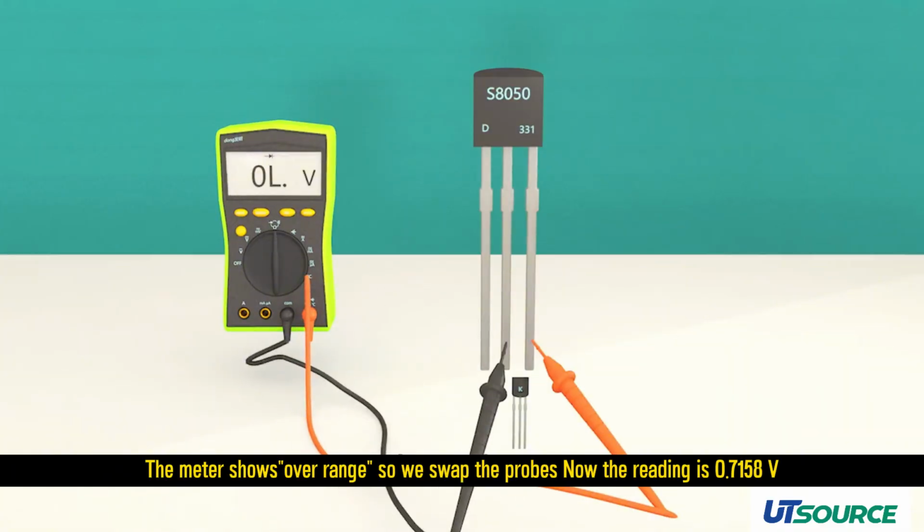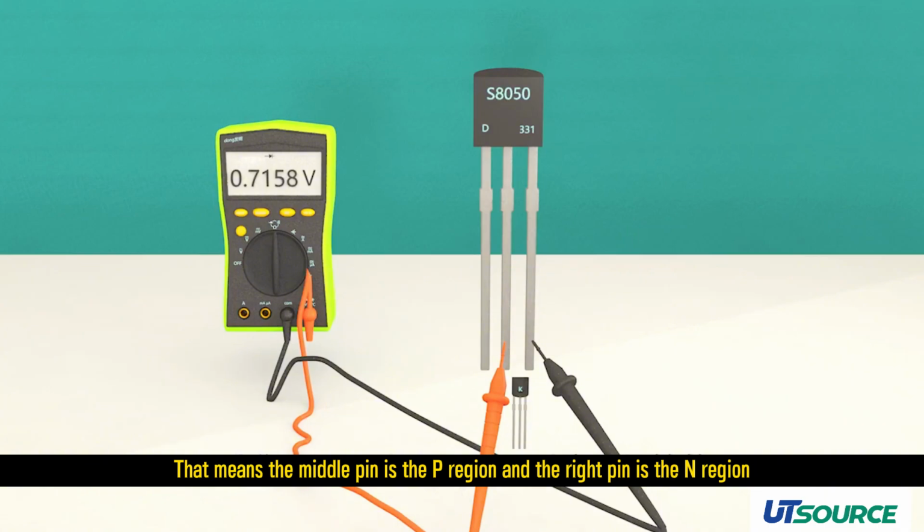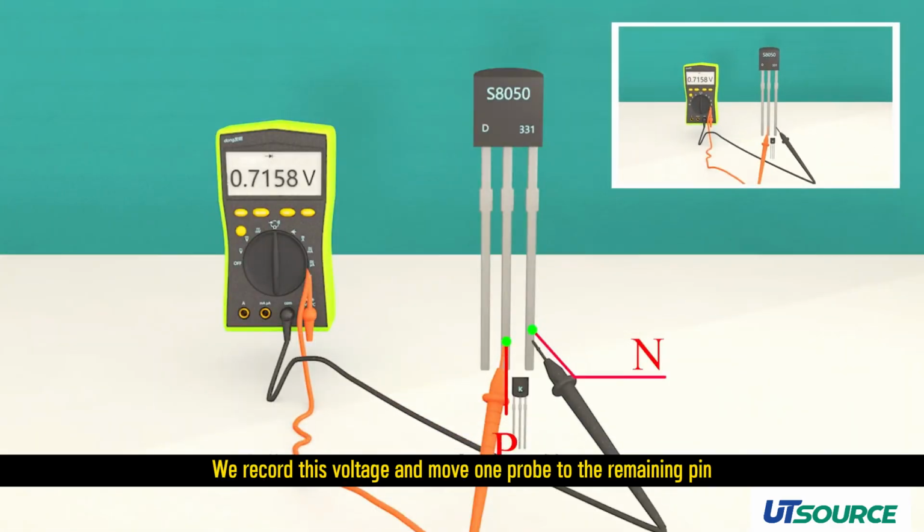The meter shows over range, so we swap the probes. Now the reading is 0.7158 volt. That means the middle pin is the P region and the right pin is the N region. We record this voltage and move one probe to the remaining pin.